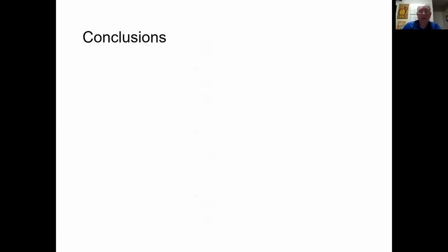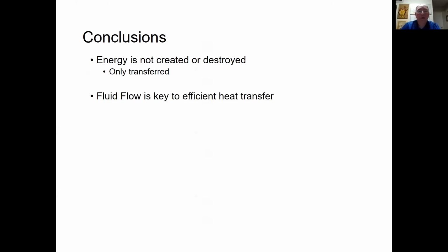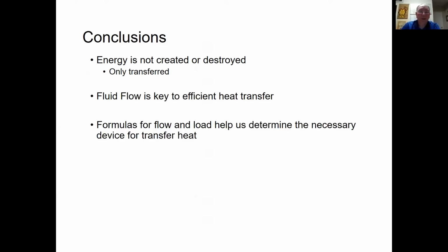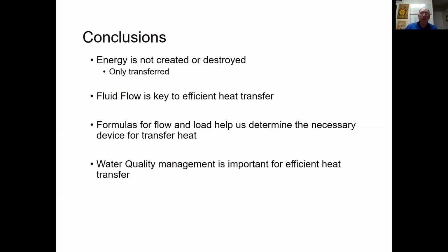Okay, with that said, the conclusions are: energy is not created or destroyed, it's only transferred. Fluid flow is key to efficient heat transfer. The formulas that we use for flow and load help us determine what your load is and what the necessary device is to achieve that heat transfer. And water quality management is important to maintain your efficient heat transfer.